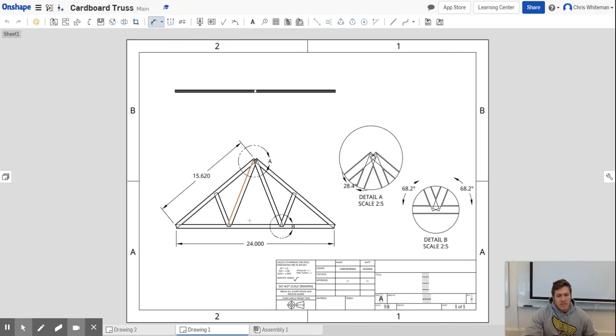use them. Now, when it comes to rules of dimensioning, you don't want to cross dimension lines. So like, for example, this one, we'll have to include this one inside. And since we know this piece and this piece are the same, we don't need to include it twice. So we know this one and this one are the same. So now all we have to do is dimension this one, and that gives us our length.